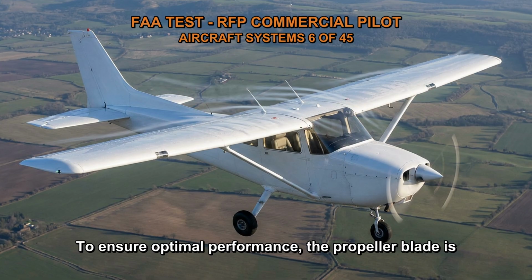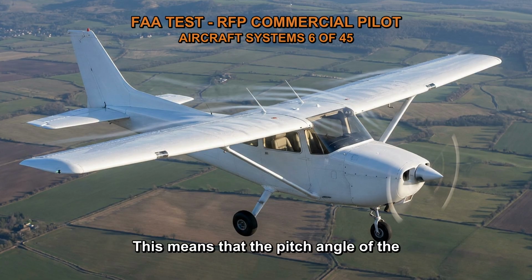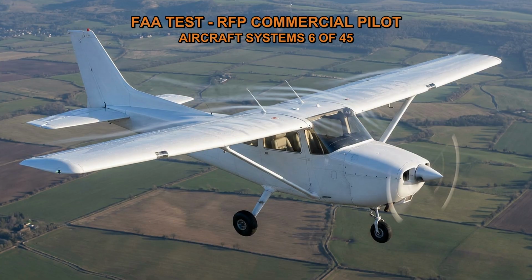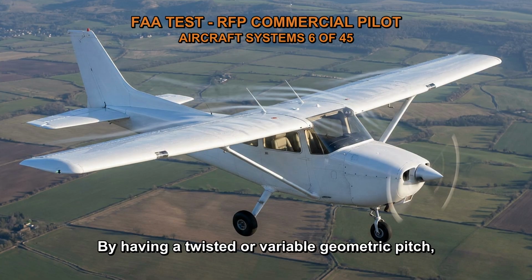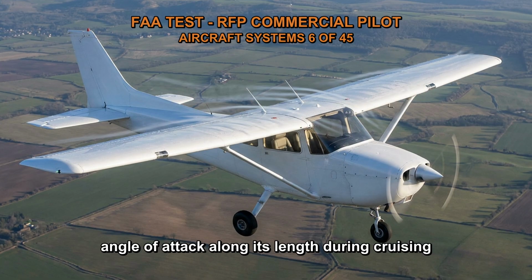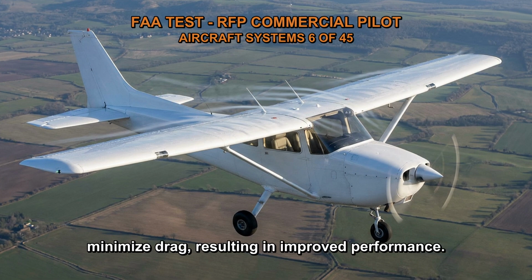To ensure optimal performance, the propeller blade is designed with a varying geometric pitch along its length. This means that the pitch angle of the blade changes gradually from the hub to the tip. By having a twisted or variable geometric pitch, the propeller blade can maintain a relatively constant angle of attack along its length during cruising flight. This helps to optimize the propeller's efficiency and minimize drag, resulting in improved performance.